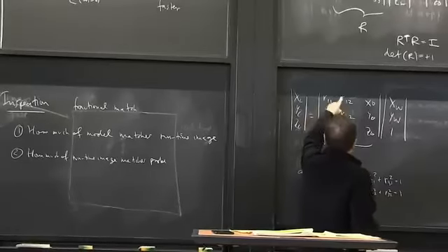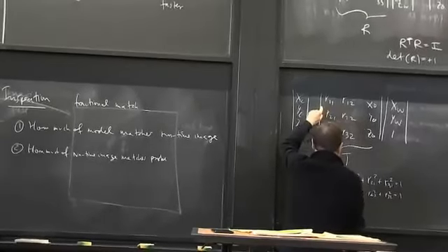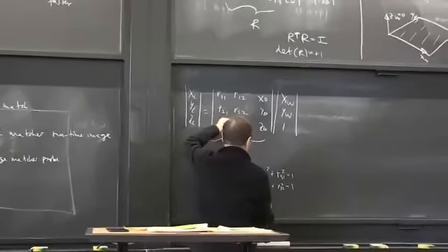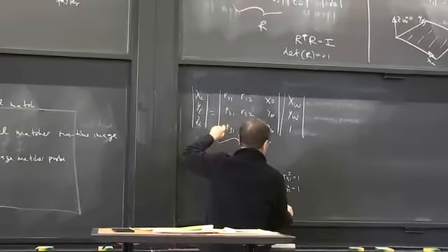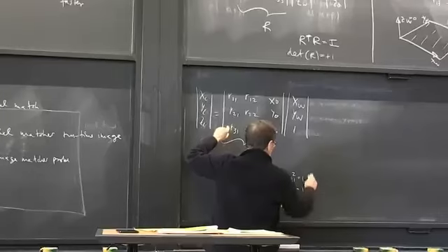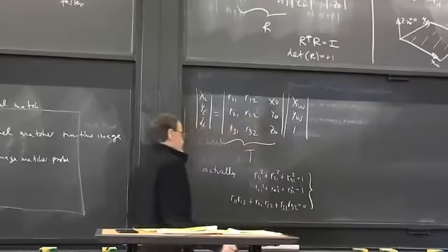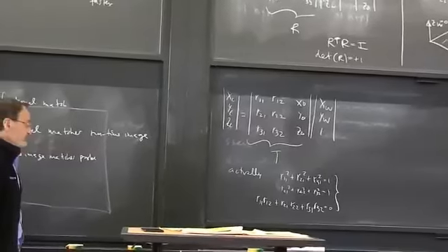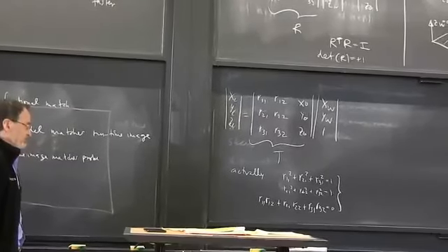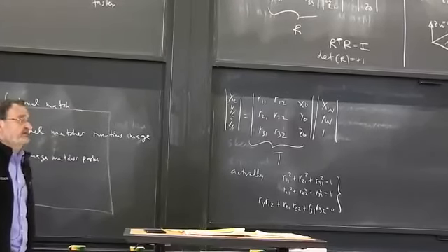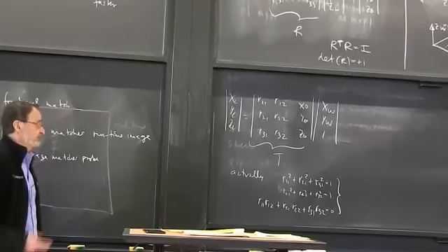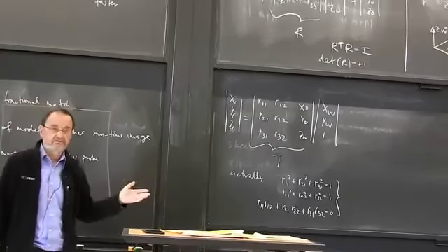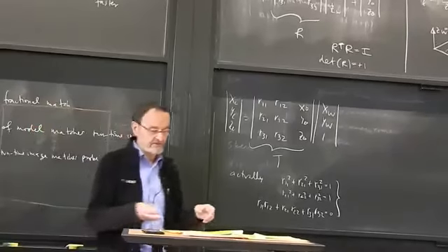These have to be orthogonal. So R11 R12 plus R21 R22 plus R31 R32 has to be 0. Okay, so this matrix T should really satisfy those 3 constraints. And let's add things up. So it has 3 by 3, it has 9 elements, 3 constraints, that leaves us 6 degrees of freedom. That's correct.